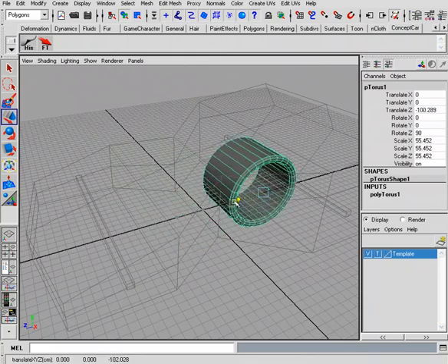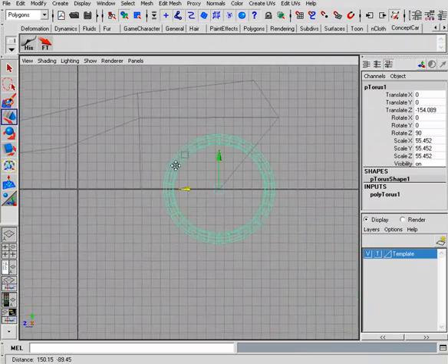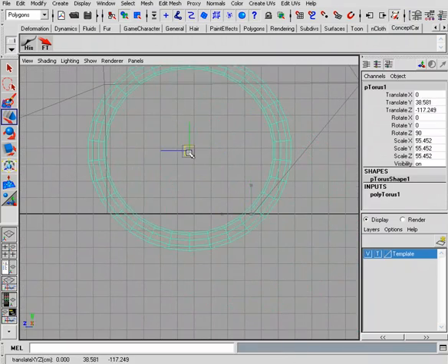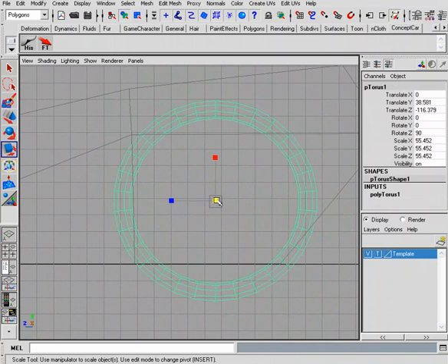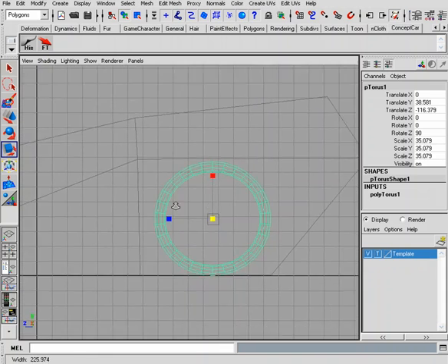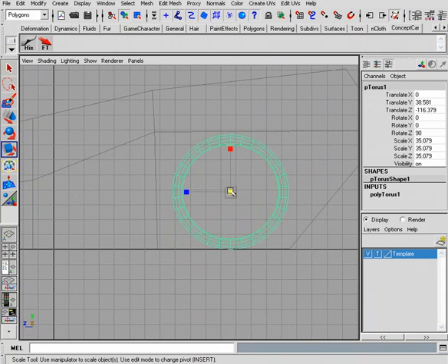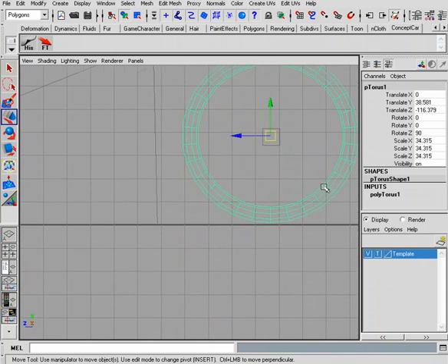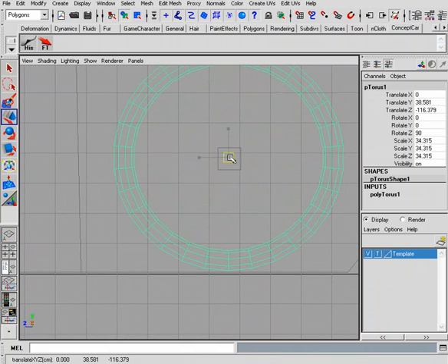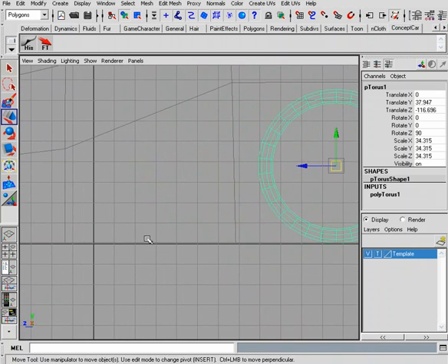And let's move it from the side view, and we'll match up with our axle template that we have here, if that's what you're using. And go ahead and scale it down a bit. So you put your center right at the center of the axle template, and then just scale that down until the bottom of the tire contacts with the grid line there.